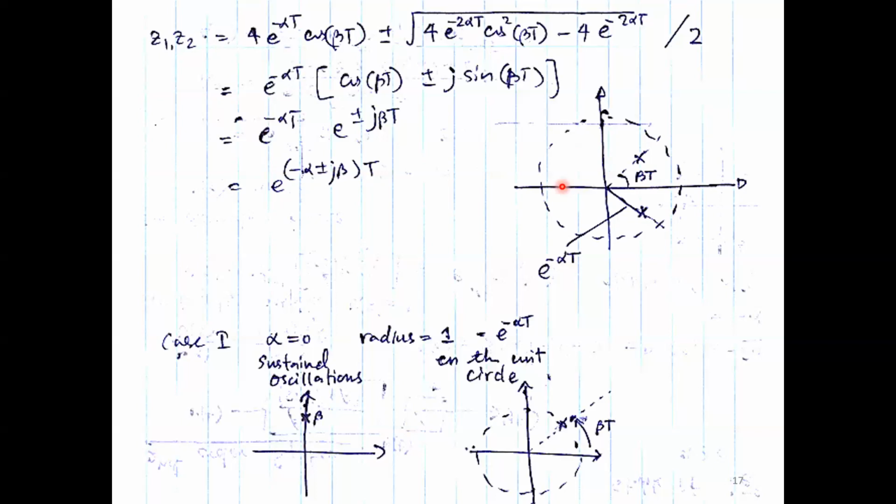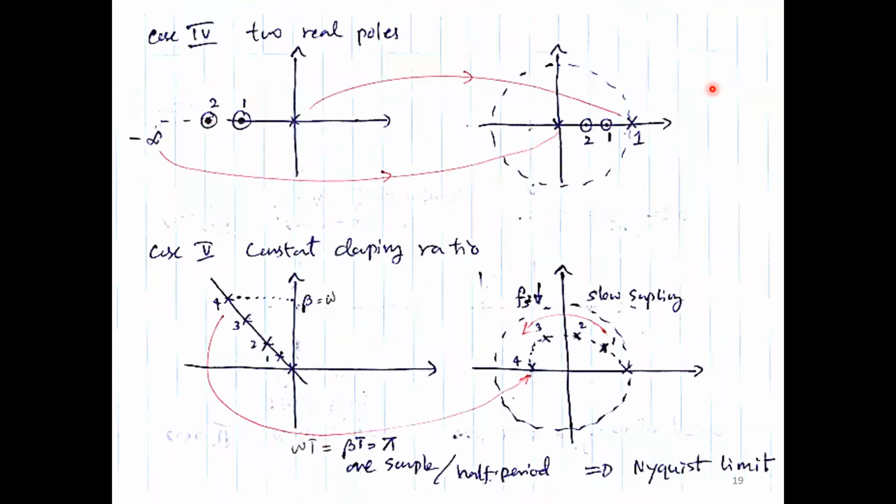If you further increase the time between samples, you are below the Nyquist frequency, and the system will malfunction. If you close the loop through a sampler operating below the Nyquist rate, you're not going to create any meaningful action in the control.